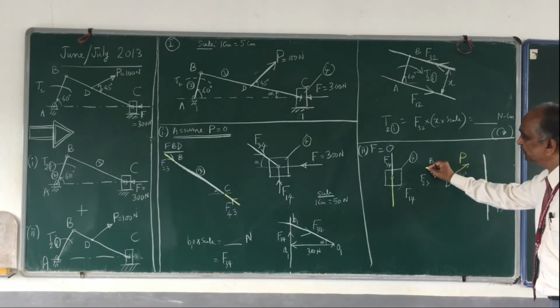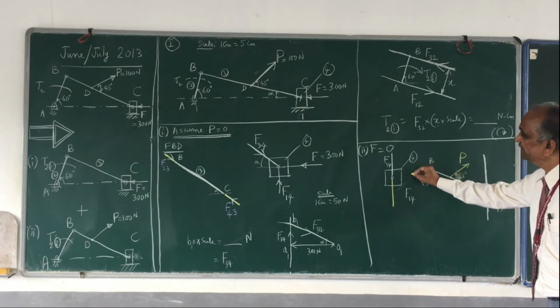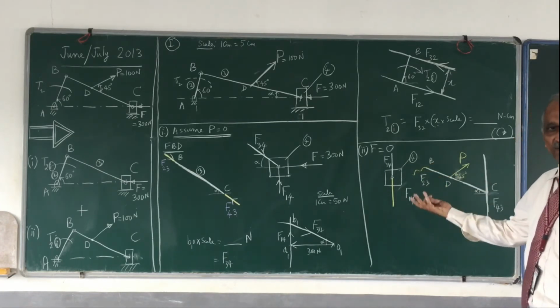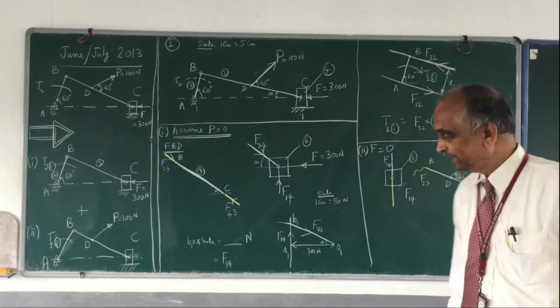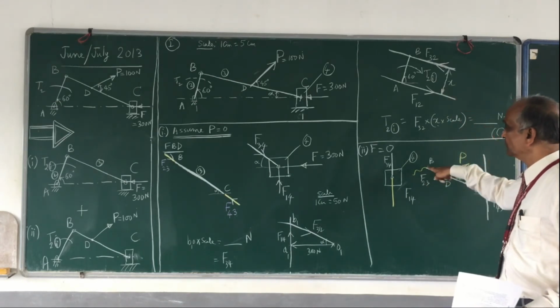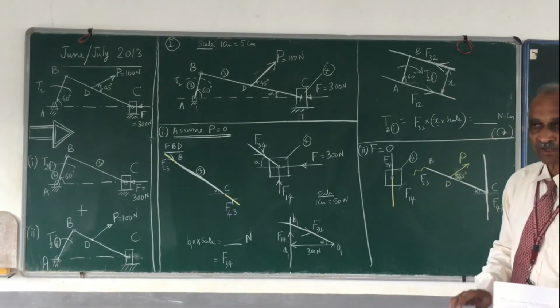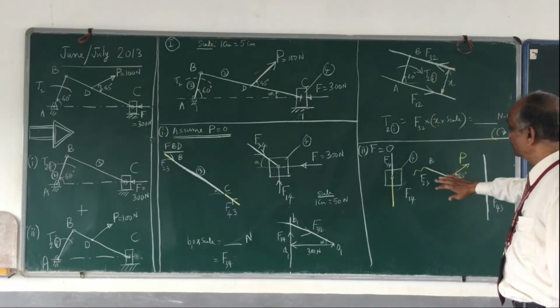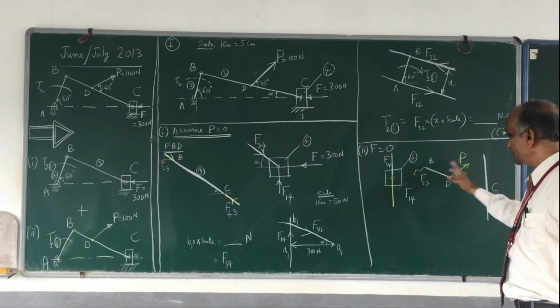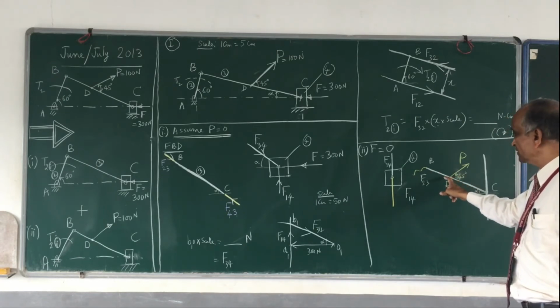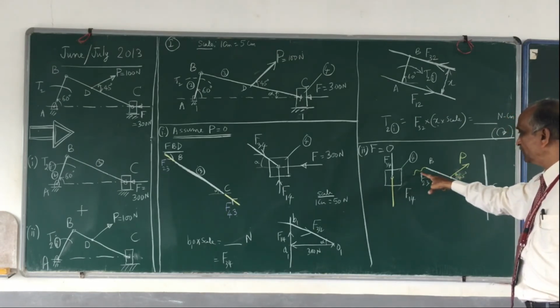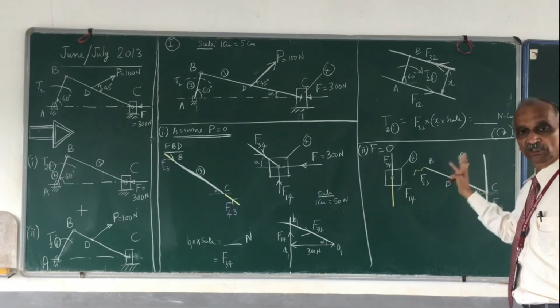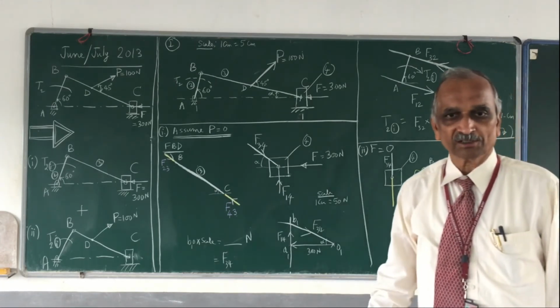Okay. So now this force F23. Right now, let me show it as if I don't know the magnitude. I don't know the direction. But I know that this force will pass through point B. Okay, so now go back to our earlier discussion. What is this system? This is link 3 which is subjected to 3 forces. I don't have any torque on anything.